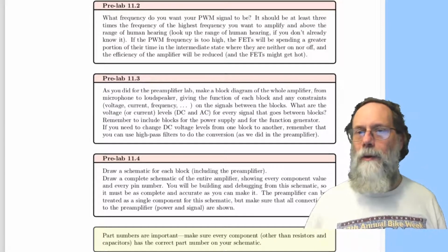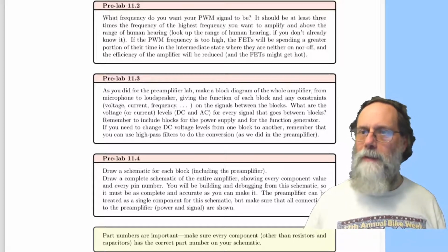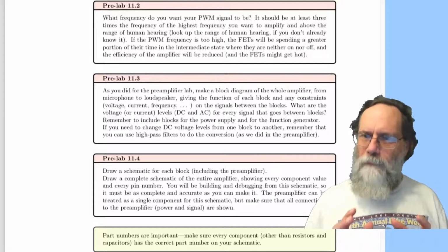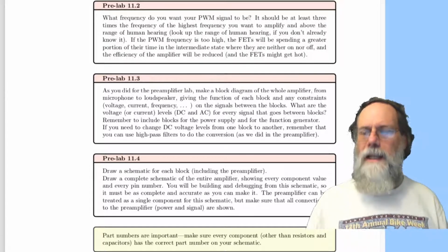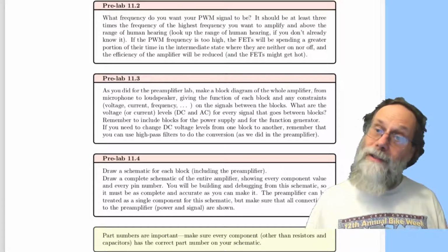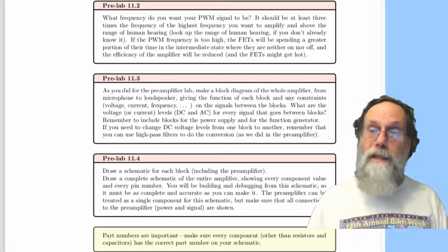Make a block diagram of the whole thing. Label a function of every block, and I do mean the function and not the part number. The function of a block is what it does, not how you implement it. And a lot of people have been doing things like saying, oh, this is a, and then putting a part number. That's appropriate for a schematic.